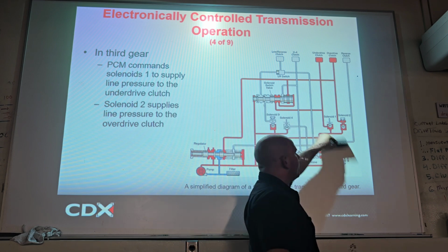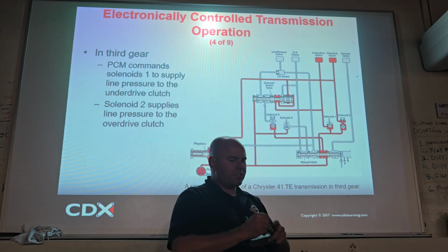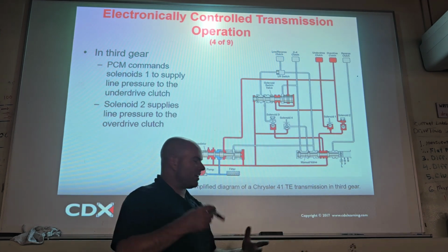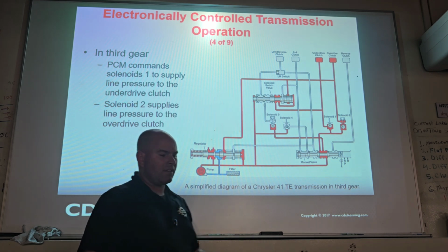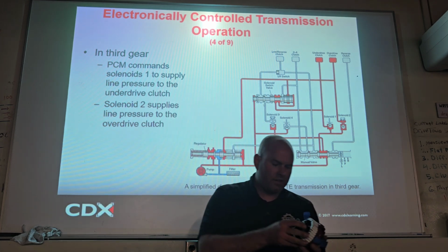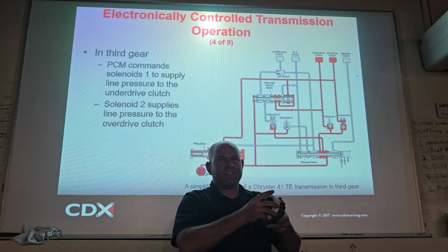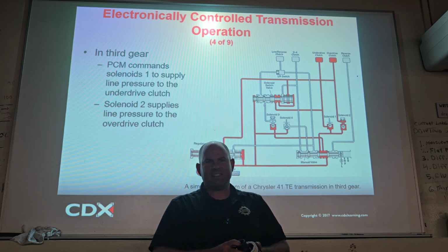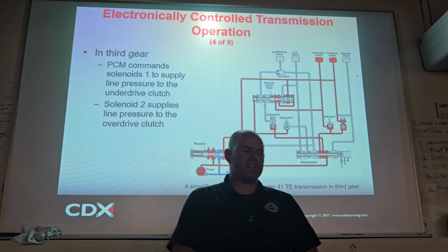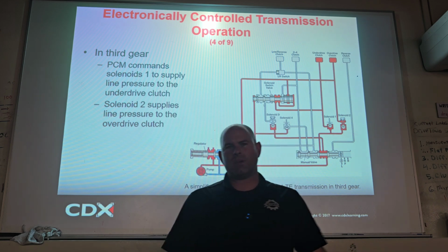That's kind of interesting. If we overdrive one gear set and we underdrive one, what do you think the net is? We underdrive one and then we overdrive one. Don't they cancel each other out probably? Direct drive, third gear. Have a nice day. That's how you make direct drive.